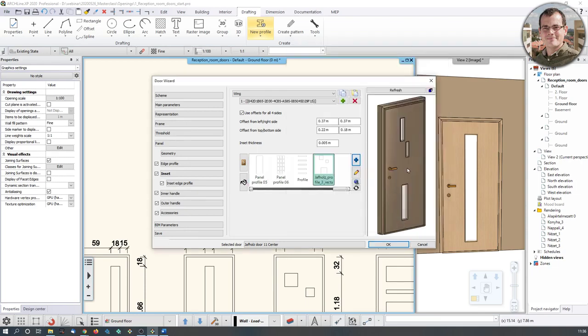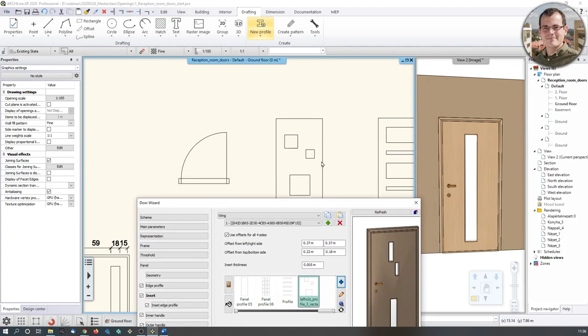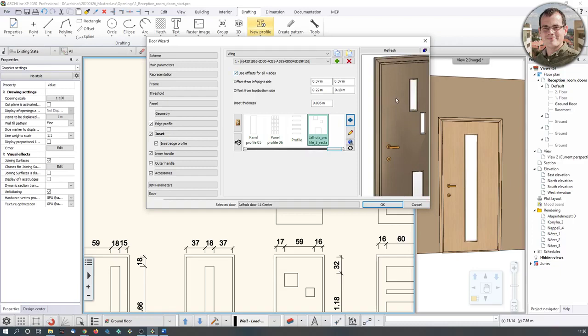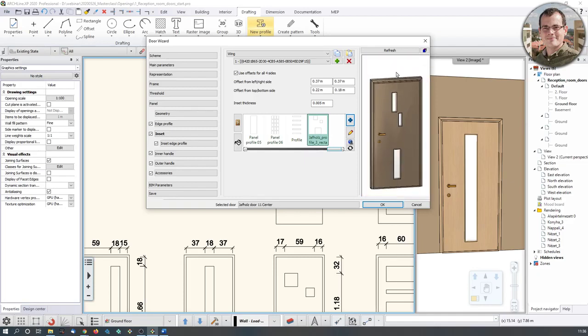like that. Okay, but this is a problem here. So even though I defined how the profile should look like, they are too narrow. So why is that? Well, that is because the software has presets here, sort of inherited from the earlier version of the door, when it had sort of like a regulation for 37 centimeters from one side and 37 centimeters from the other side. So it sort of squeezes the profile into this very narrow area.